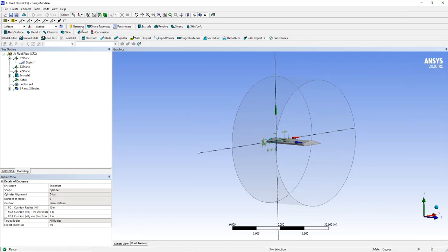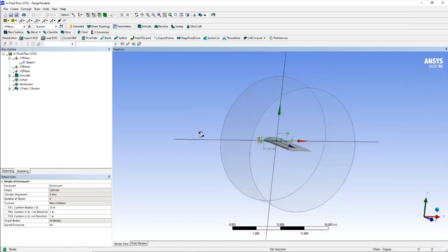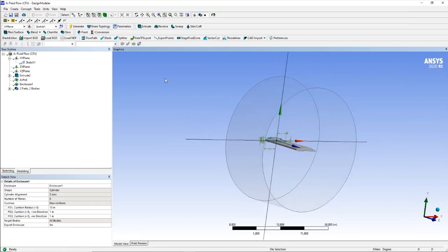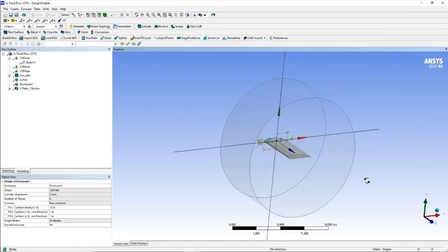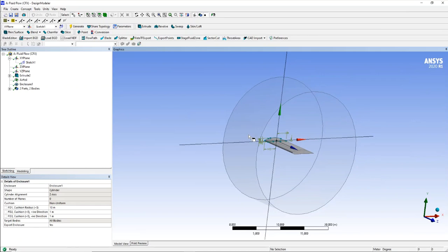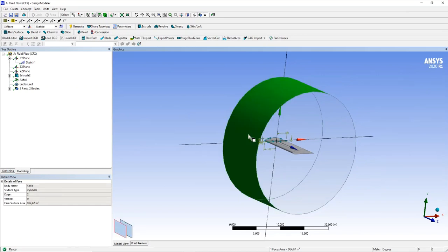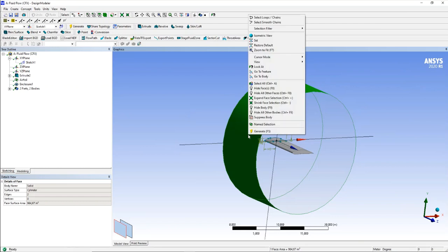Go to generate, sometimes from time to time click generate, and now we have to choose the direction from where our air enters the cylinder. And that's also a little trick. I will come to this later. We will not define any inlet and outlet. We will define an opening. And this opening means it's not defined if the air enters or if the air exits a boundary condition. That's a special, really cool boundary condition.